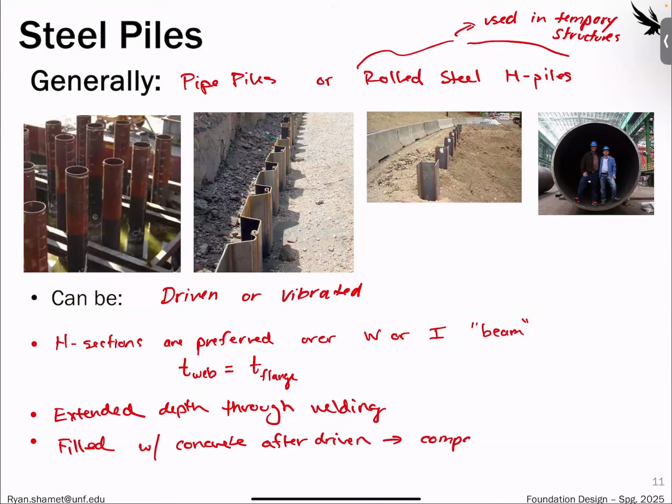So it's kind of a benefit of both sides, where you get the benefit of driving a pile, like an easily driven pile, and then you can fill it with concrete to increase the density of the pile or lower the center of gravity or whatever you need. Maybe it's high axial capacity, so you need to have that really thick, like full or heavy dense pile to account for that. So you can kind of have the benefit of both worlds in there.